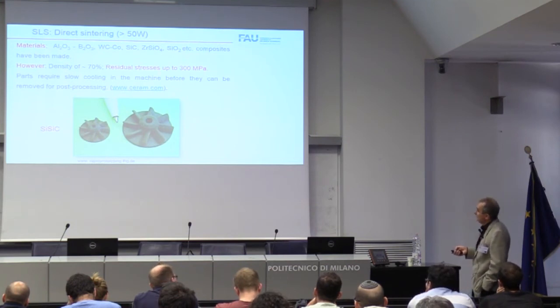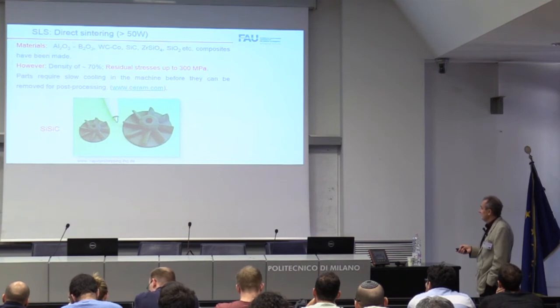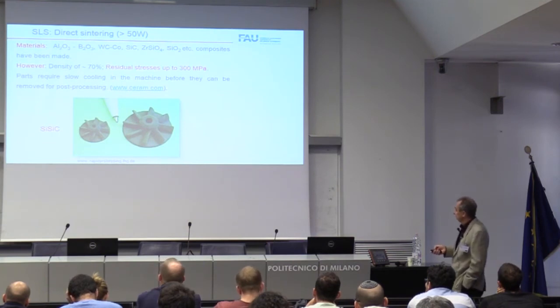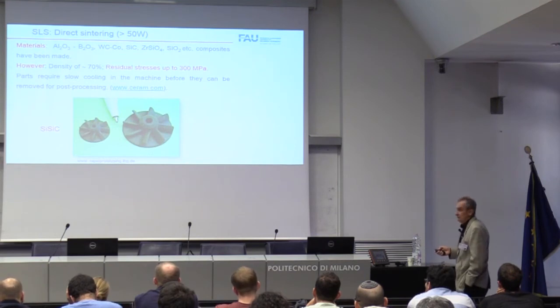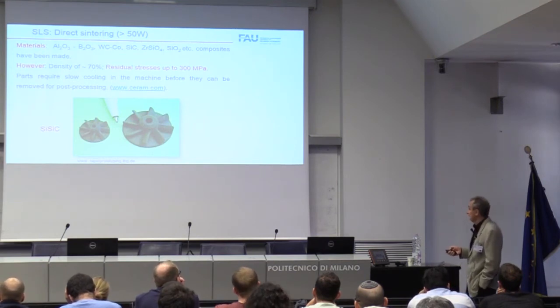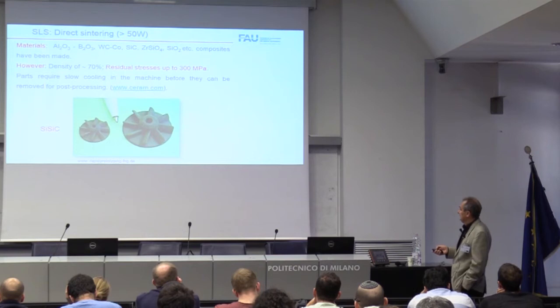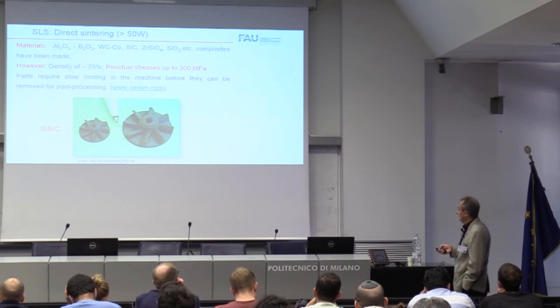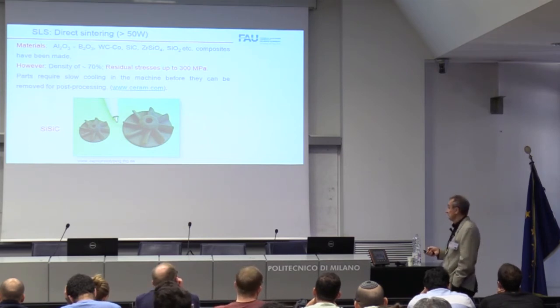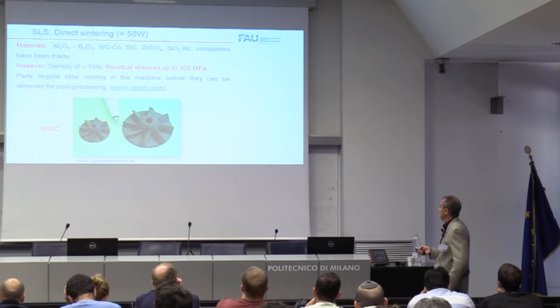But just now, if you think about direct sintering, you need, of course, very high energies of laser, up to 50 watt, and of course you receive components, several components, and you see density only 70%, the rest of binder, the rest of materials which put it together.